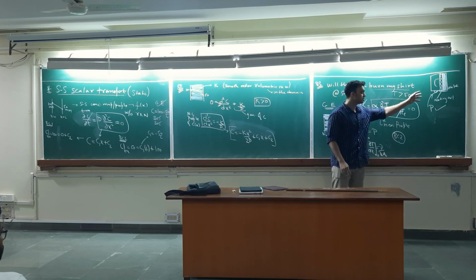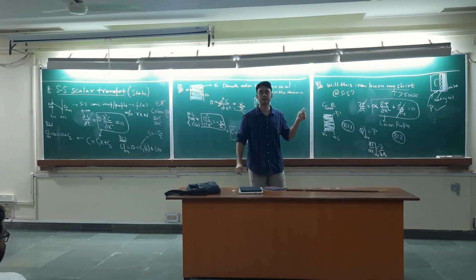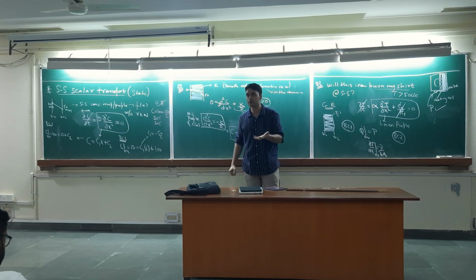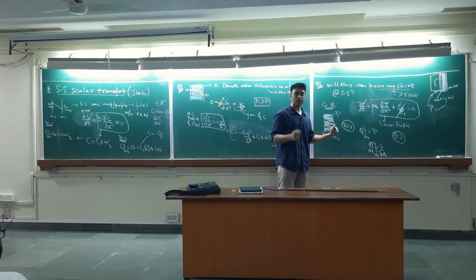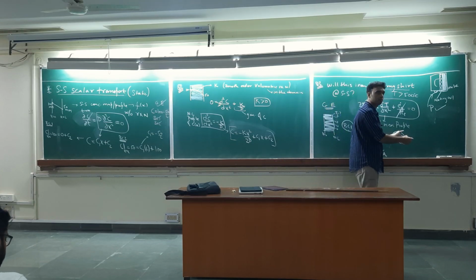But look at this system. You have a metal, a power P is being provided. This temperature is unknown, T_L. You have to find T_L, so you cannot give it as a boundary condition. Yes. So this iron, you've kept it, right? It's open to ambient, right? Mixed boundary condition. So what should I write?